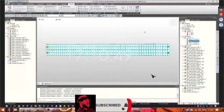Okay, the scheme has been chosen to allow the thermal expansions in both x and y direction, releasing the degrees of freedom for this support in x direction, for the y direction in this support, and both directions for the third one. The first is fixed. In this way, we prevent stresses due to uniform temperature load.